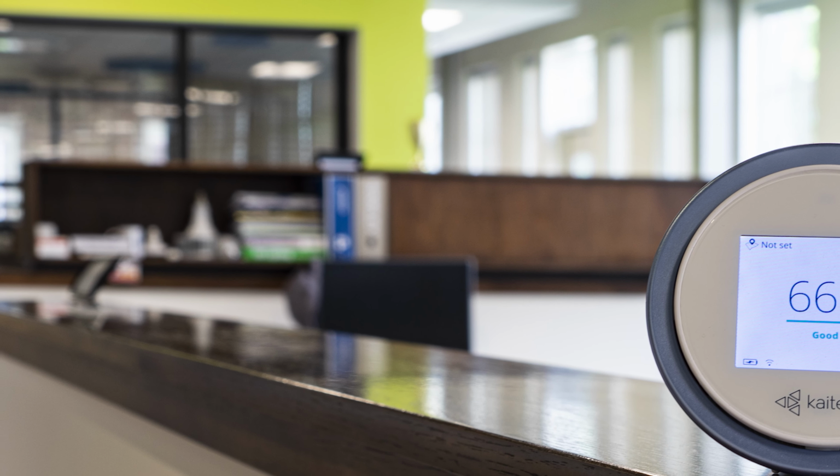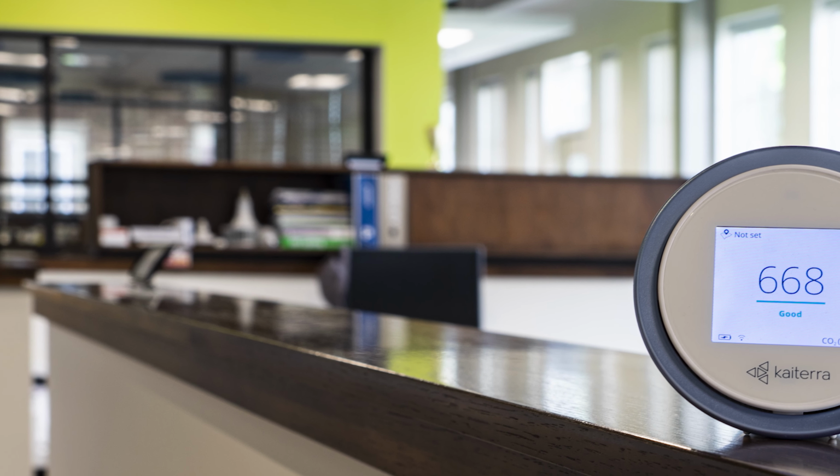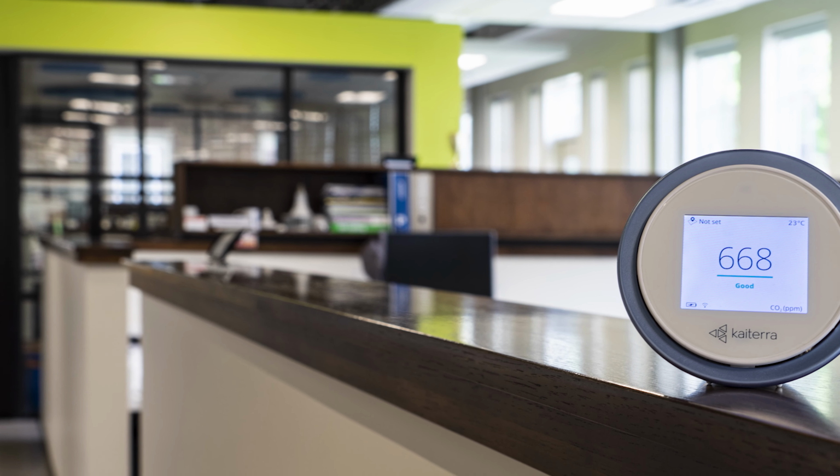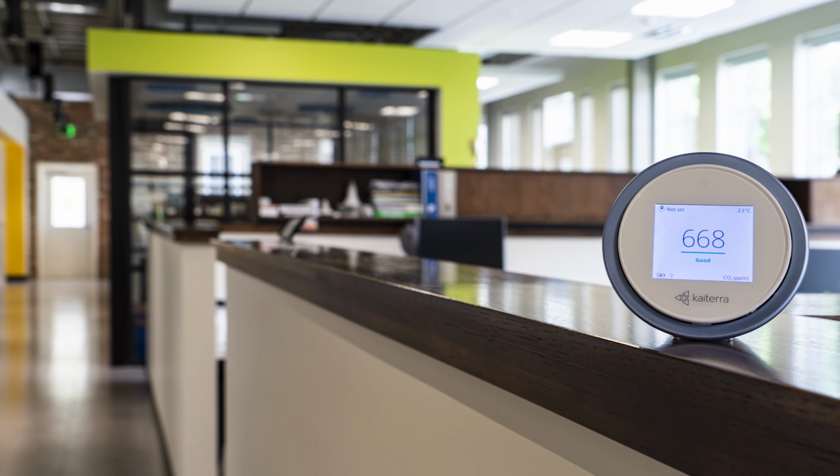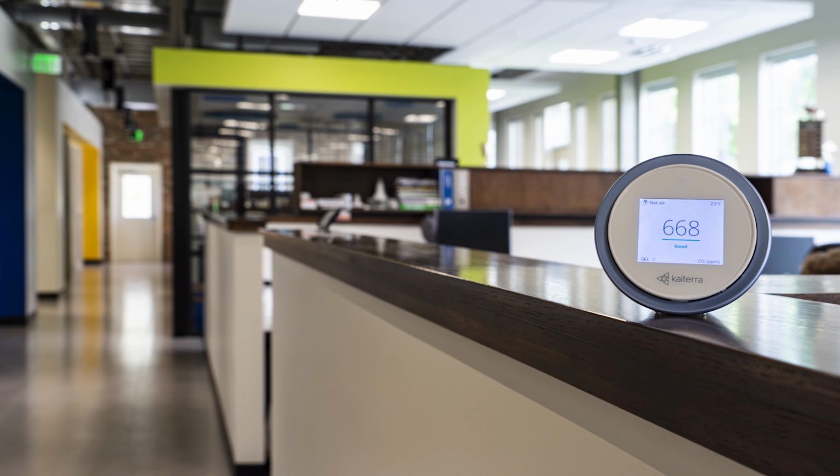We're also really focusing on indoor air quality. So the opportunity to over-ventilate a space above code, increase the amount of outside air into a space, is going to drastically lower our CO2 levels in the building, which improves cognitive thought. With the improved air infiltration and better passive and active filtering systems, we can help prevent against virus spread. But we can also drastically reduce the amount of PM 2.5 and PM 10 particles that are really chronic particles in a space, chronic particulate matter.